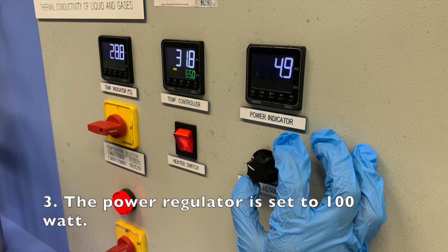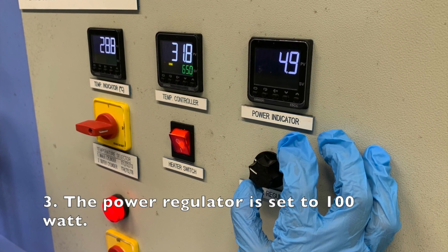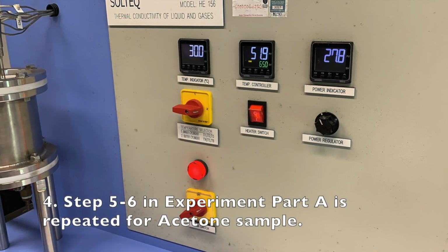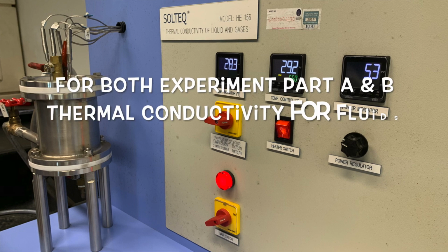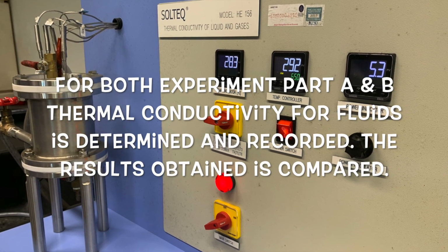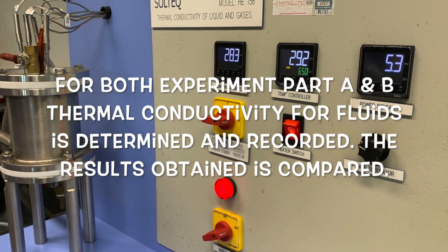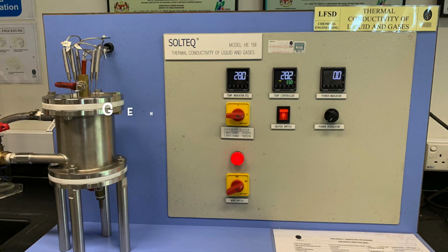The power regulator is set to 100 volts. Steps 5 to 6 in experiment part A are repeated for the acetone sample. For both experiment part A and B, the thermal conductivity of the fluid is determined and recorded. The results obtained are compared.